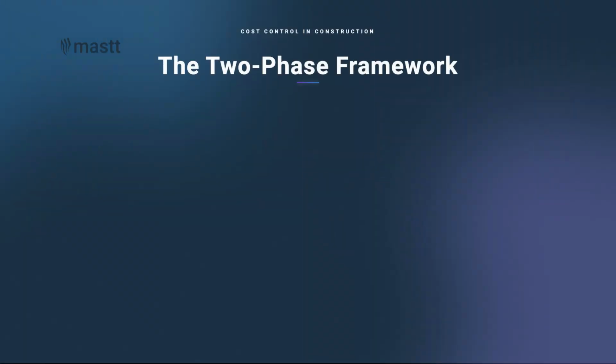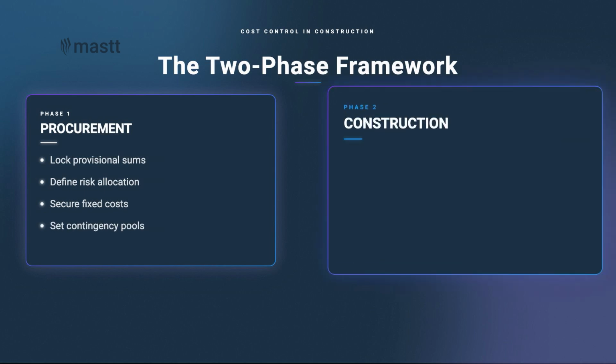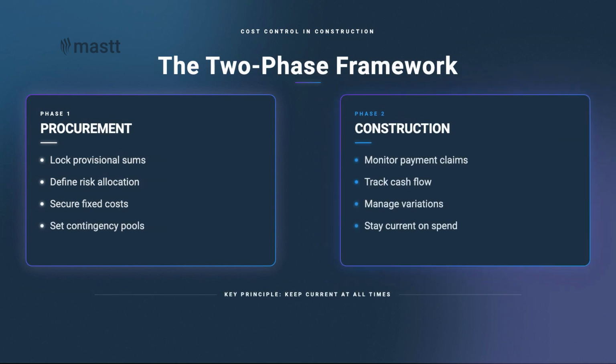And would that mean cost control starts at the very beginning of the project with the budget? Yeah, it's starting at the procurement phase. So it's making sure there's a clear understanding of risk, and that any risk that sits with the client side is actually defined and has its own separate pool of contingency available, as opposed to an overall holistic project contingency. Because each risk has its own potential cost and time impact, so you break those down to build up a total contingency number.